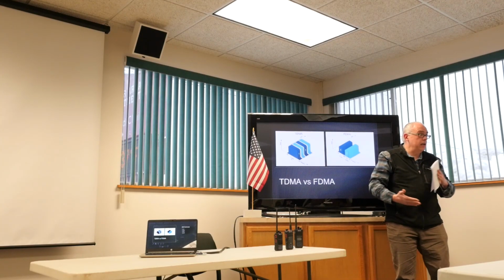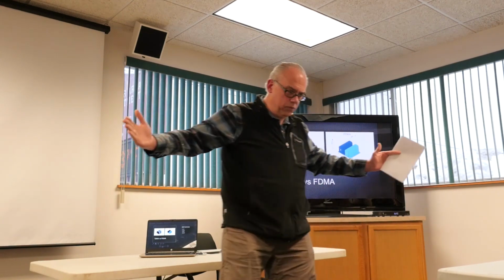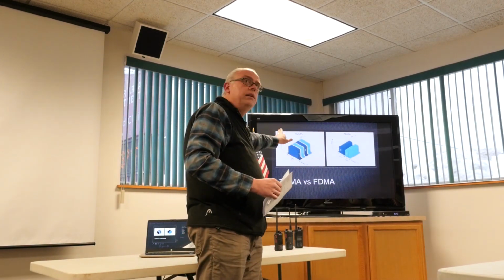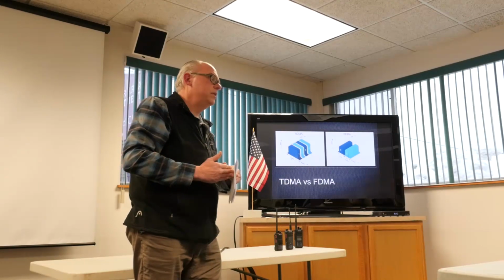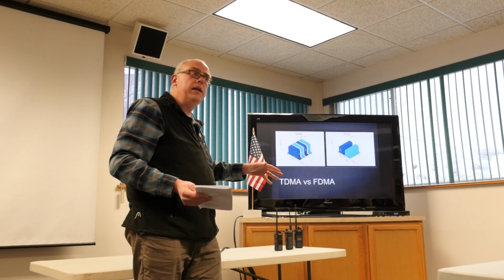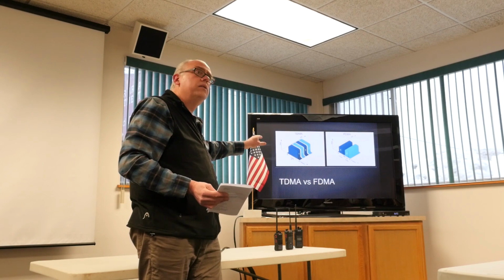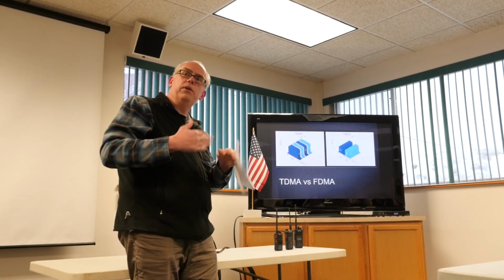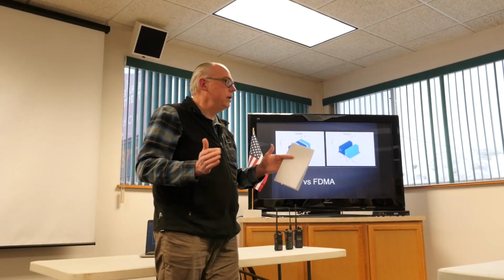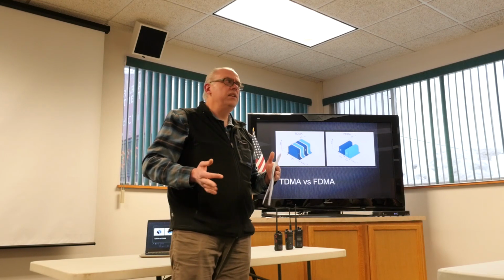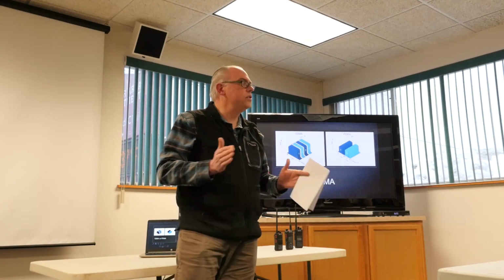You could technically have a better audio quality because we've got more bandwidth, but because we're slicing our time in half, that lowers our data stream. So when you do the math, the data stream bit rate on DMR is pretty close to the same as you find with D-Star or System Fusion. So your end result is that the audio quality sounds pretty much the same between the three different digital modes.